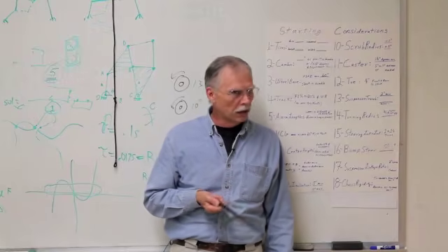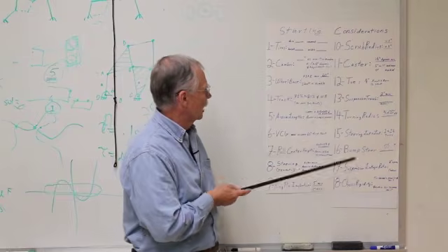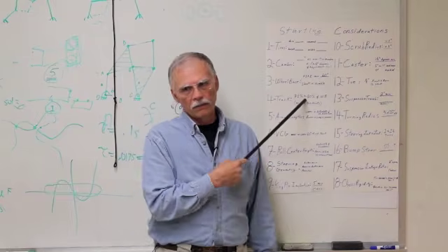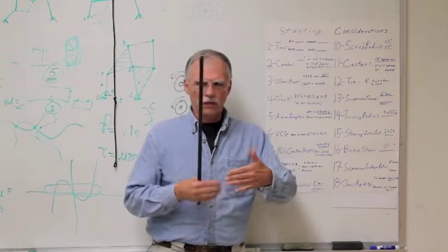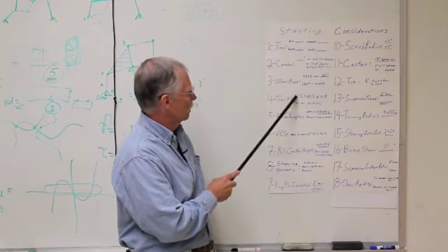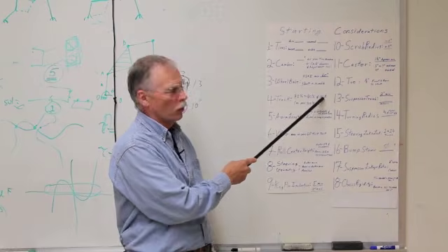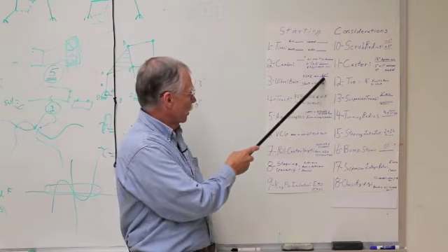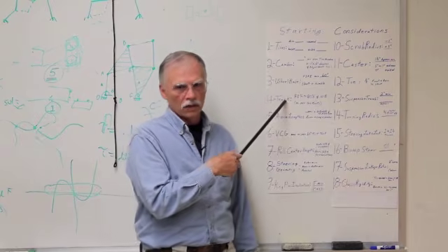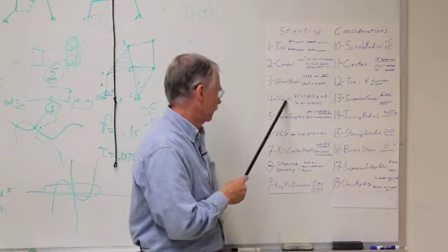If you look at go-karts, you will find they have an aspect ratio of about 4 to 5. They're about 5 parts long, 4 parts wide. So the track needs to be 75 to 80% of the wheelbase. Whatever the wheelbase is, take 75 to 80% of it. That will give you a great starting point for your track dimension.